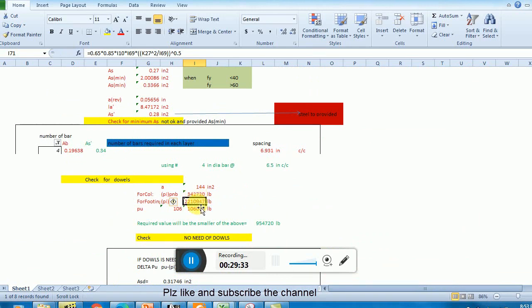This is the bearing pressure which is transferred from the column, which the column exerted on the footing, and this is the footing bearing pressure. So here I have to change this to 0.7, although in the new version of ACI we have to use 0.6. So once I change this coefficient, that is 0.70, and let's see.